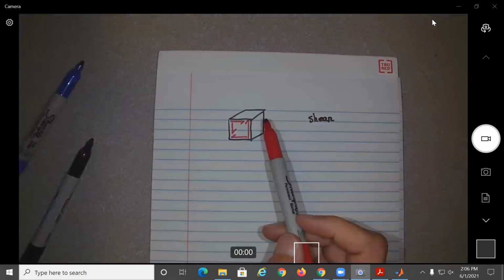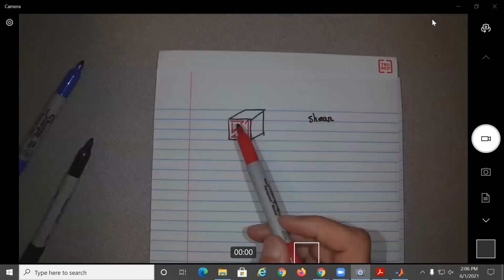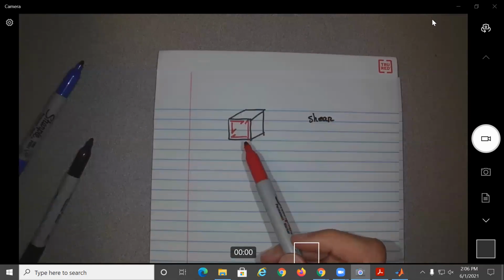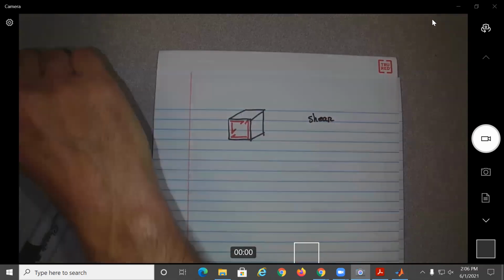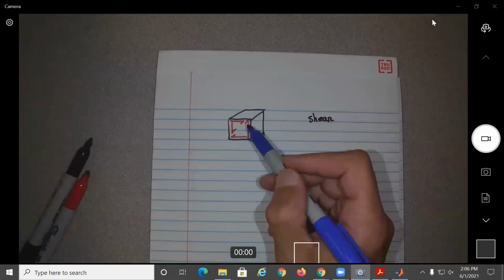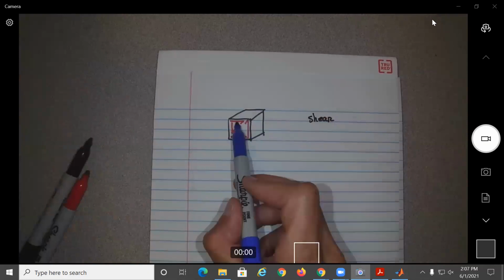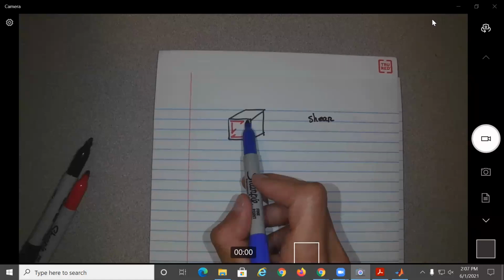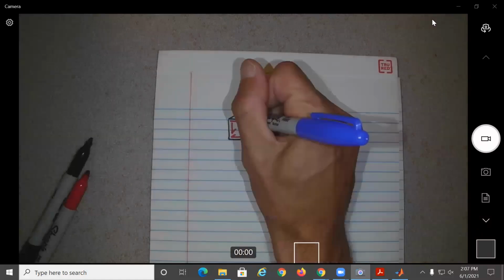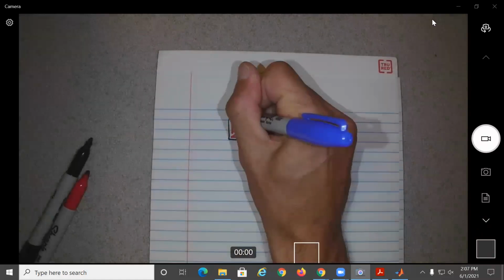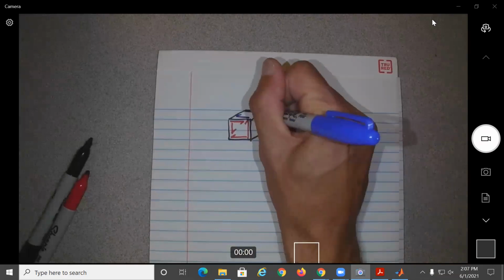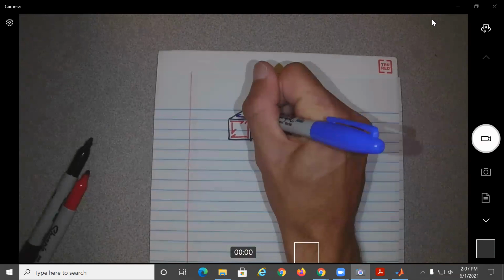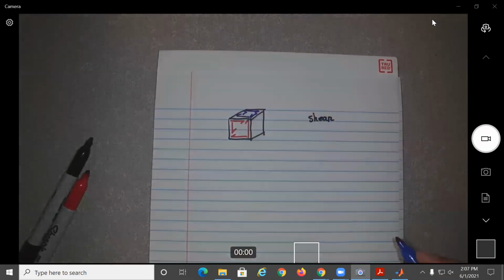Why are those two forces in opposite directions? So that we have summation of forces equal to 0, no? Otherwise, we'll be moving. So if this is the shear on this face, what's going to be the shear on the other face? It needs to be 0 also along this line, so you will have a shear force in the opposite direction. And then everything will get reversed over here, this one will be down, and this one will be going up. Does that make sense?